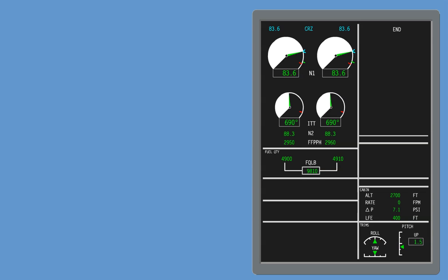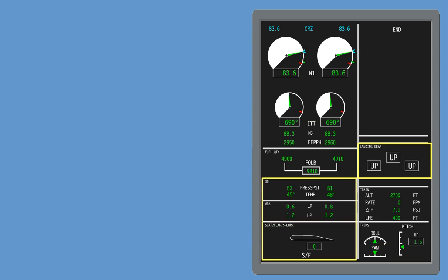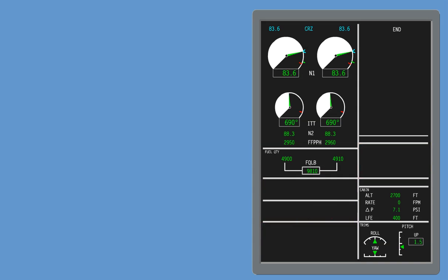The ICAS will be decluttered if the following conditions are met. The aircraft is flying in a clean configuration. Flap and gear up for more than 30 seconds and none of the decluttered parameters have been exceeded. If these conditions are met, the following items are decluttered during cruise.